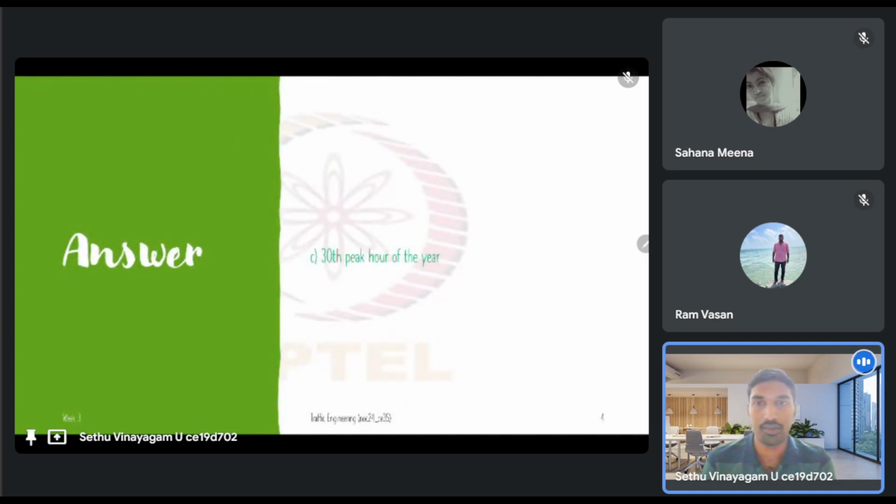So we saw this concept of directional design hourly volume, right? So when we want to design a particular facility, we design it for the peak hour condition, right? Because that's where we expect the demand to be the maximum, right? So during the peak hour is when the demand is maximum. So that's the demand that we want to design our facility for, right?